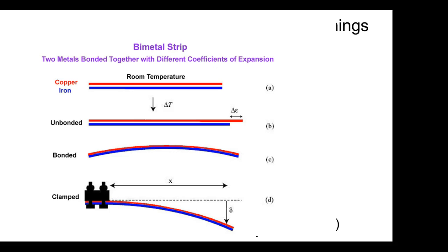So the size of the conductor, what metal it's made out of. Different metals have different conduction, right? You understand that? So we call it the gauge, then the length of it, and then the temperature. Most metals, their resistance goes up with temperature. In fact, all metals that I know of. No metal that I know of, resistance goes down. Of the known metals, unless you find something else big.